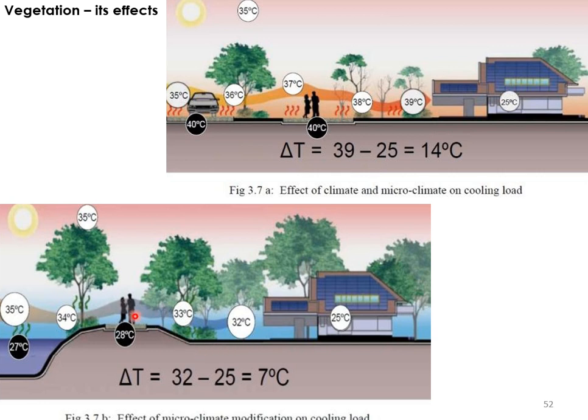and there is a lot of slope and vegetation, etc., and there's going to be a water body. So you cannot really understand, of course inside your house it is 25 degrees Celsius, and when you come outside the house, there are a lot of large big trees which are also called deciduous trees maybe, and there's a very small walkway or pathway, and it is covered by two trees. So this becomes a mutual shading element for the pathway itself, and the reduction of the paver also can give you a lesser amount of heat.